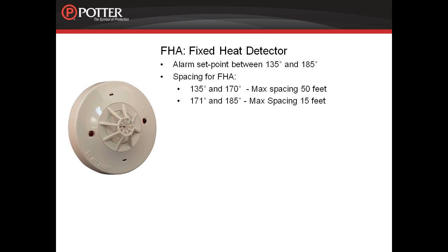The spacing of this device is dependent on the alarm set point. As the temperature setting increases, the spacing decreases. With an alarm set point between 135 degrees and 170 degrees, the maximum spacing is 50 feet. Between 171 degrees and 185 degrees, the maximum spacing is 15 feet.